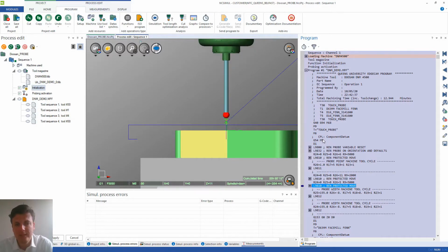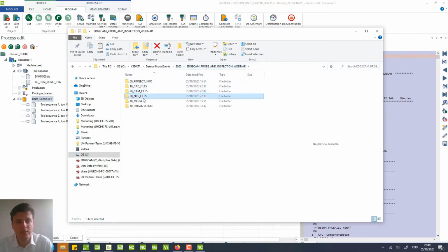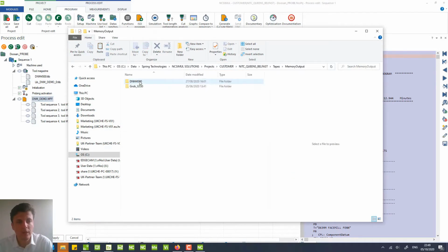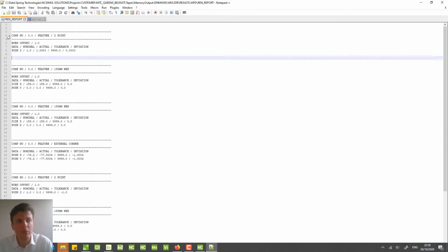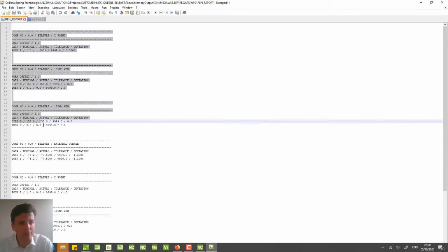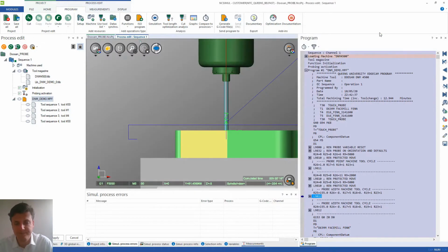And because R19 equal 1 was outputted, that's basically the function updating the G54 on Siemens 828. And you can see R23 equal 1, that generates the report. Because NCSimul has a functionality for write reprint, it generated this Renishaw underscore report file into my memory output folder.